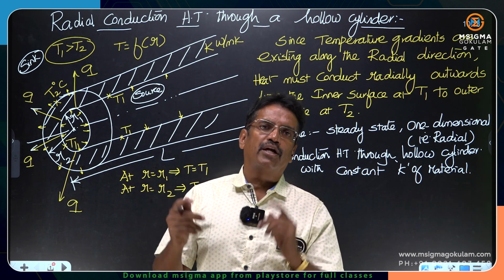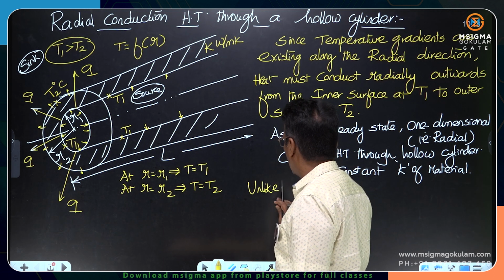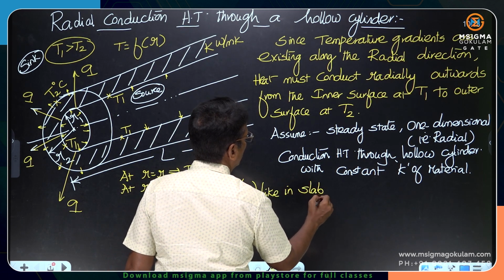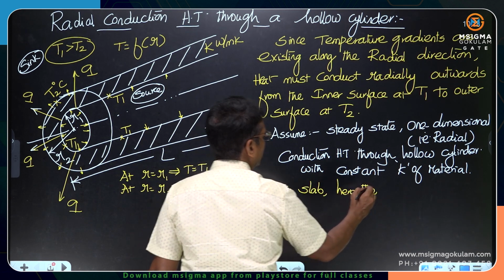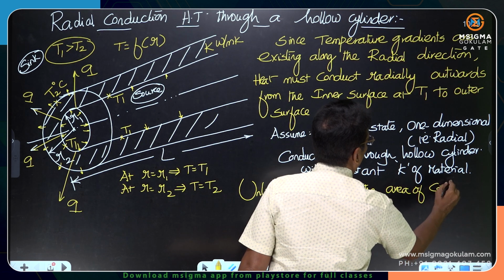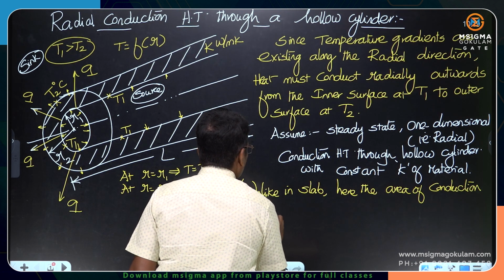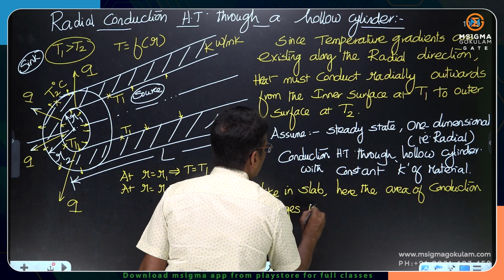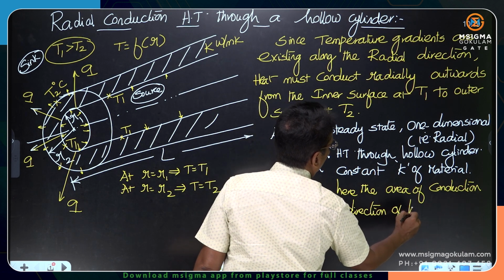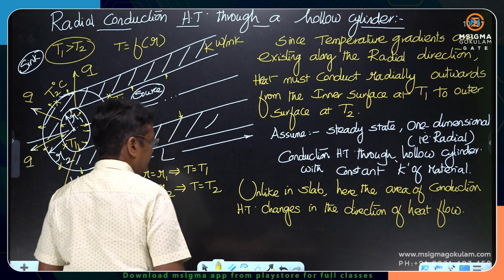And I am going to write that unlike in slab, here the area of conduction heat transfer changes in the direction of heat flow. Okay, that is very important.